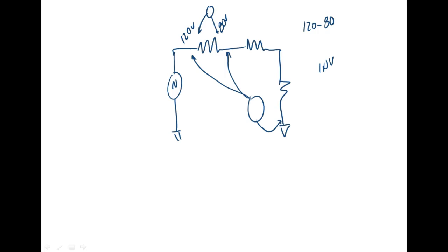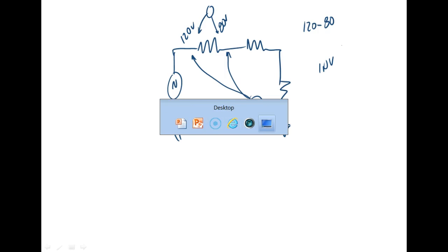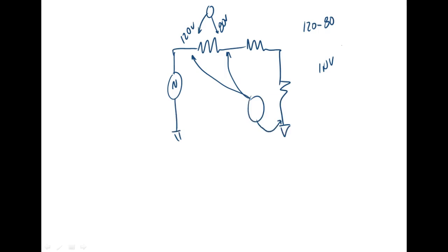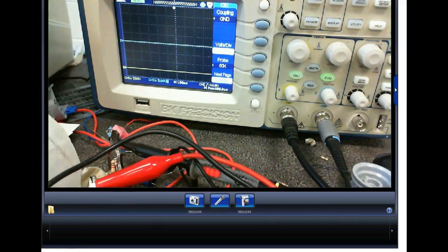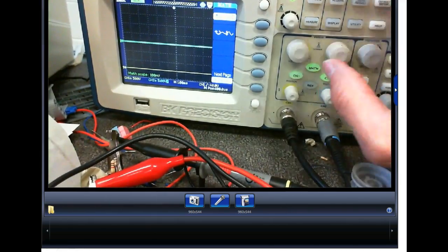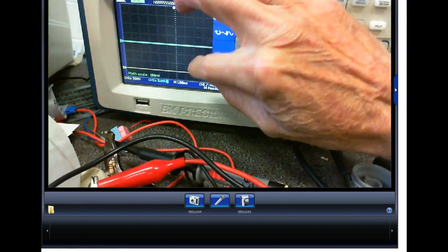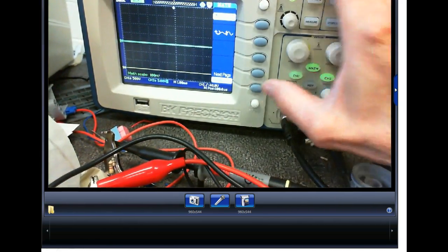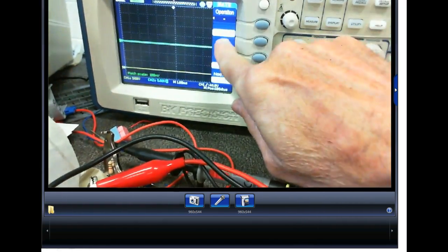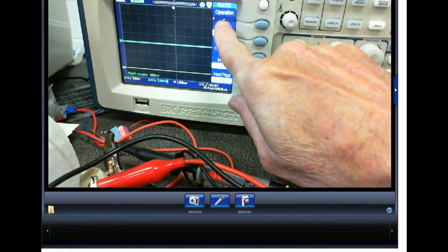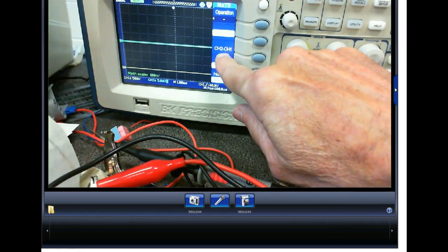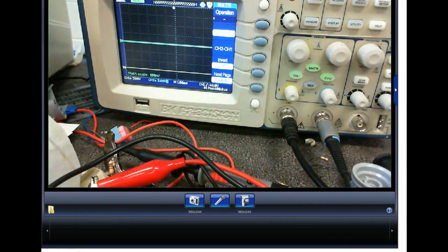Now, on the digital scope, we just come up here and go to our math function. So right here where it says math, then it throws another section on here. And then by now we got it set up to do what? You'll see the sign? Subtract channel 1 from channel 2. Now in DC it would make a difference. You'd have to figure out channel 2 would be your common and channel 1 would be the high side. On AC it makes no difference.